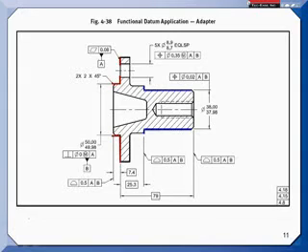I don't know that I want to give 2 great reasons to not use the pitch diameter. Functionally, it's correct. There are thread gauges out there that pick up the pitch. They're not cheap, but if this is a really critical application and you need that, a lot depends on how the thread is created. If you're using a tap, for instance, you drill a hole first, then you use the tap.